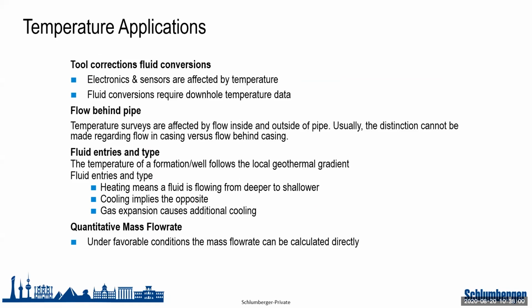So what are the temperature applications? The temperature applications are basically corrections of the sensors that are present on your production logging tool. You also use them for fluid conversions, okay? You require the downhole temperature data for that. You use it to analyze if there is presence of flow behind the pipe.